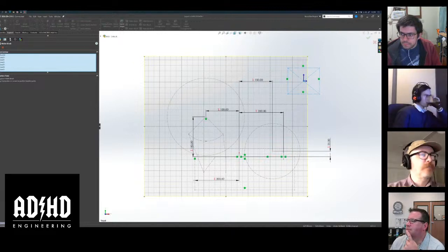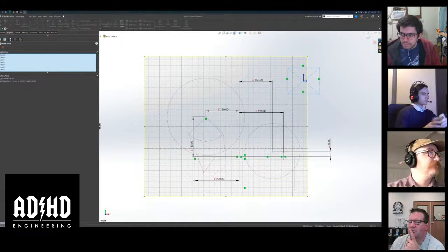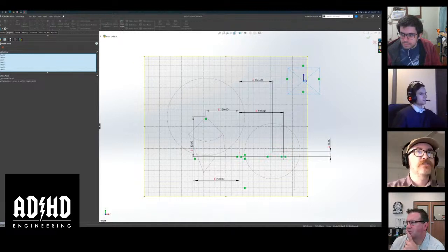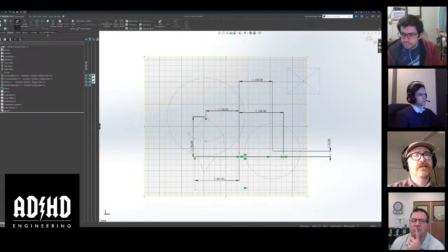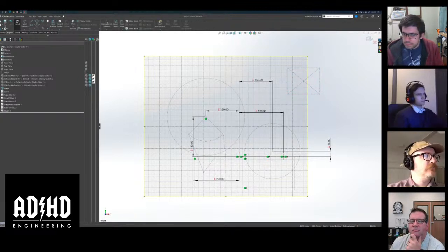But remember, we actually haven't even made the block yet. It isn't yet a block. It's still in the selection phase. So we will press the check, or I can go up here in the top right corner and check there. Okay, so now it's a block. And if you notice, it's gray. We're still in our layout sketch, and now we have a new block.